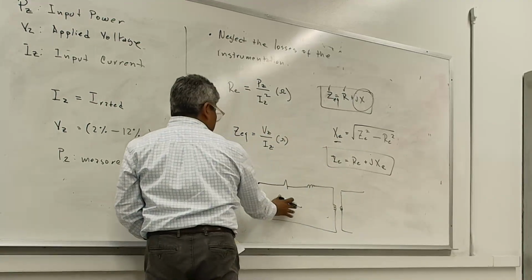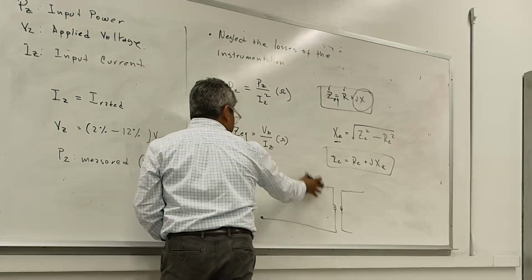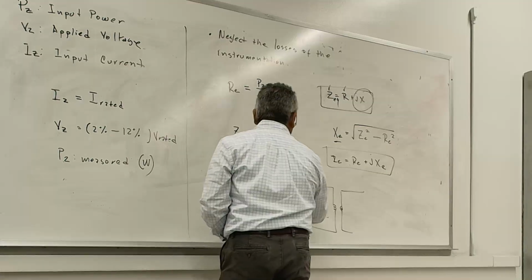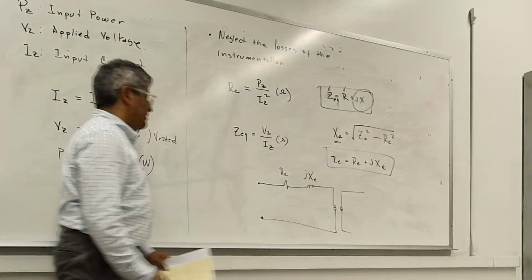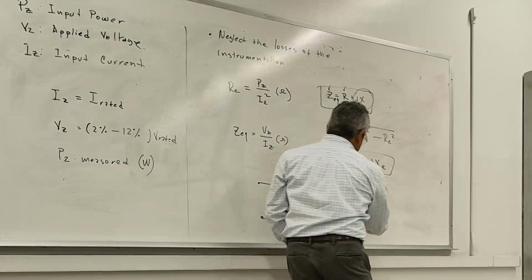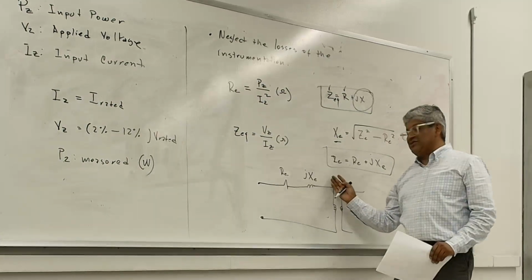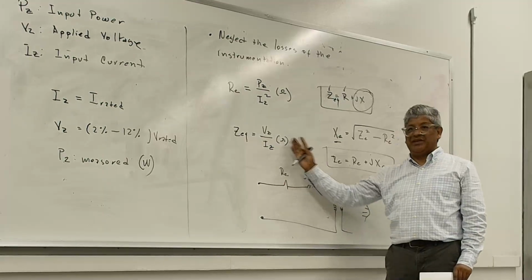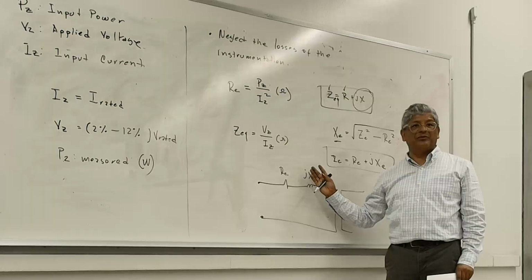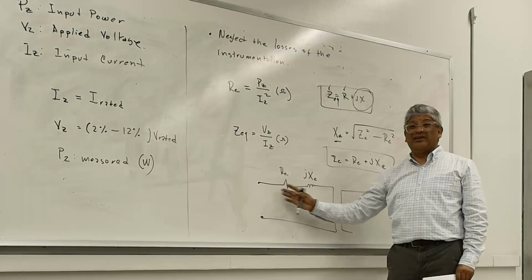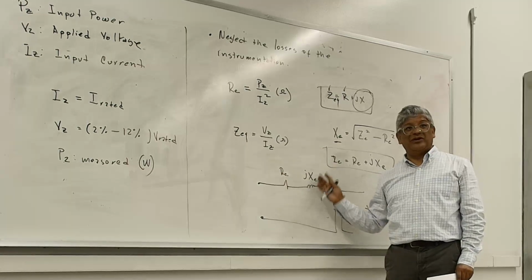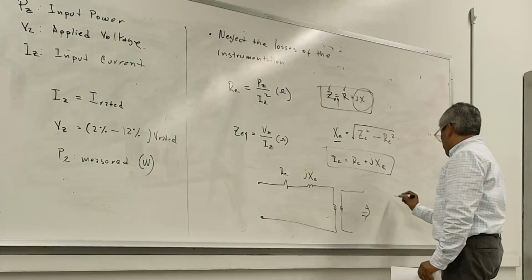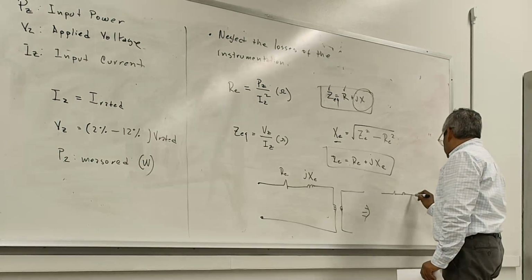So what I'm doing here then, I have the ability to do this. Remember, I'm doing the testing, taking the measurements, on this side of the transformer, right? So this becomes then my RE, I'm going to call it right here, because that's what it's called in the book. And then XE, okay? In reality, maybe I mentioned, this is what the transformer manufacturers will give you. That's what they call the transformer leakage, or they call it reactance. I don't tell where the name comes from, but this is the copper losses of the transformer that they're giving you right here. So you can say, oh, I want this model.